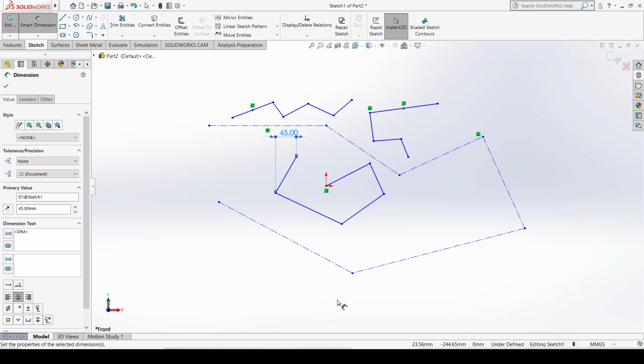Okay, this is a very good plus point for us, because when you draw anything in SolidWorks, you can draw roughly. Then you give the constraints so that the drawing becomes fully defined, and then you convert it into a 3D element. So this is the plus point here. But in case of AutoCAD, what happens? You have to define the dimensions, you have to define all the constraints before drawing the line. So it is a bit different from that software. So it is very flexible. You can give your dimensions dynamically at any moment when you draw the object or your drawing.